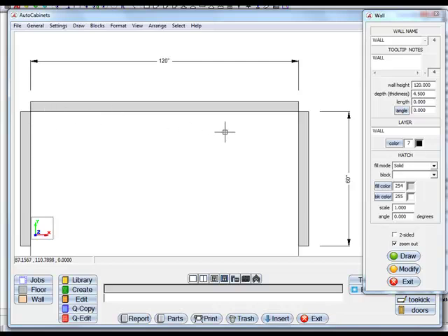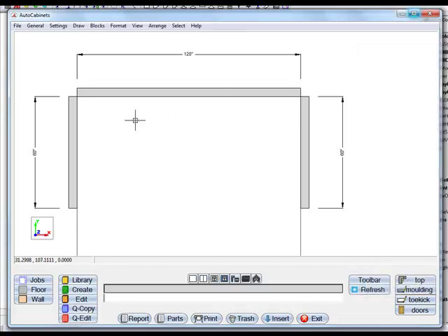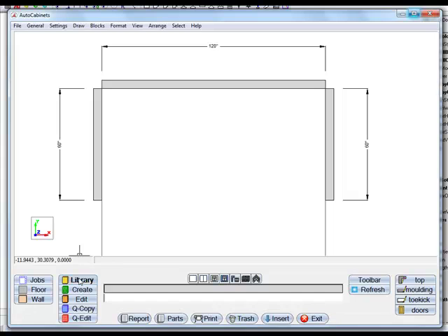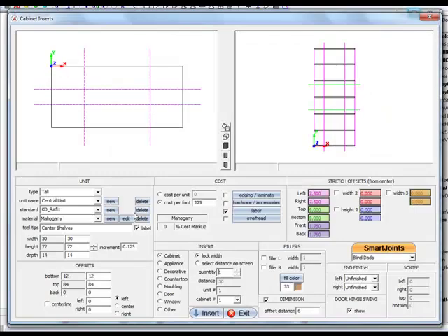We're just going to put closet cabinets across this back wall. I will close this. We'll go to the library. I'll just take this tall open unit. When we created this in the library, I made this tall opening at 30 inches length of the shelf. So let's reduce that to 24. It's 72 inches tall. It's going to be 12 inches from the bottom and 84 inches to the top, which is, I want to line up all these closet units at 84 during the closet layout.